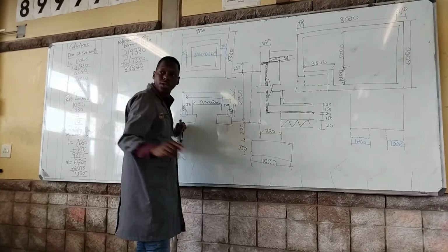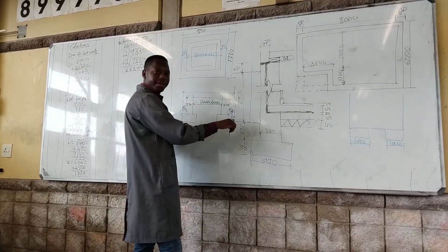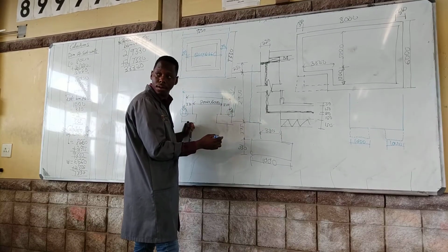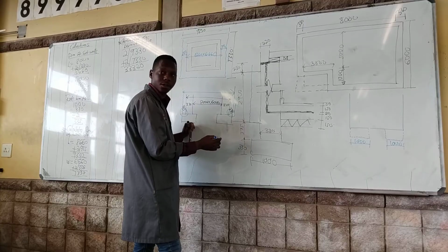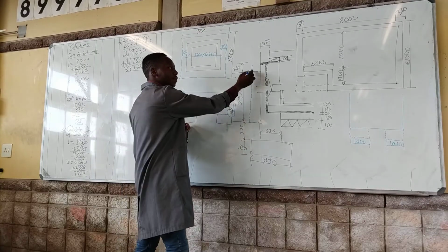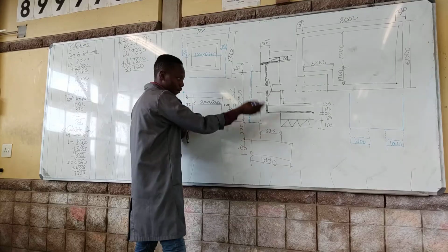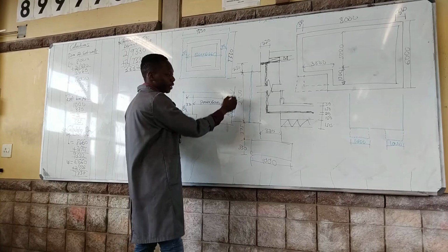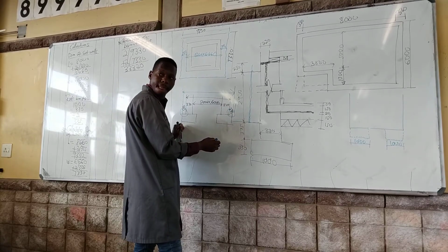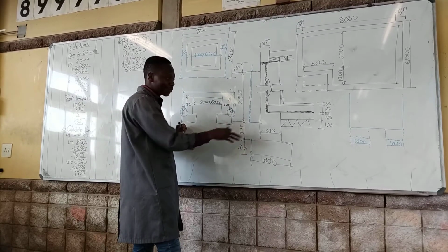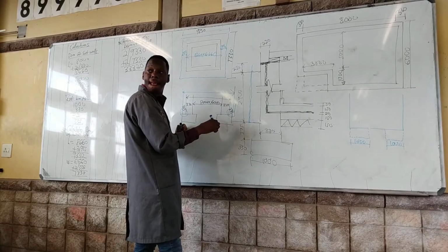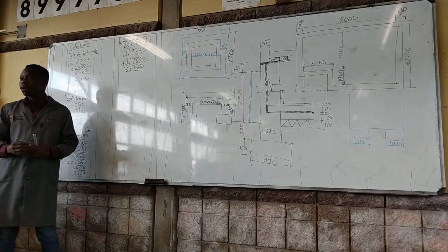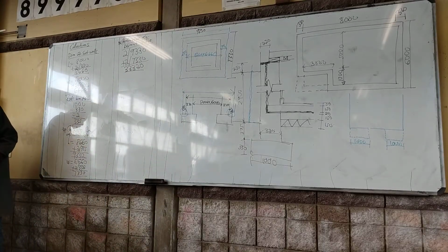Sometimes they will specify to calculate the depth of the basement hole to below hardcore. So now we are calculating the depth of the basement to below hardcore. If we check our measurement, this 2.9 starts from where? Focus on this one. Don't mind this gauge, this is a reference. And from the natural ground level to here. Do you see it? Yes.